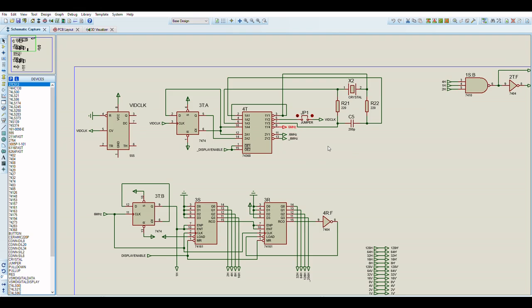This is really useful because some of the timing uses the source 6 megahertz, and then some of the timing, for example if it wanted to read RAMs or clear RAMs or whatever, uses the off cycle, or the inverted 6 megahertz clock.